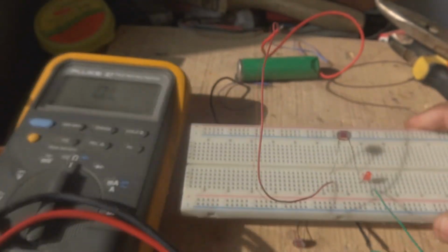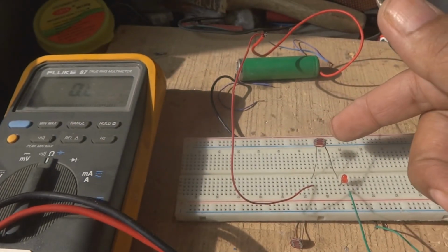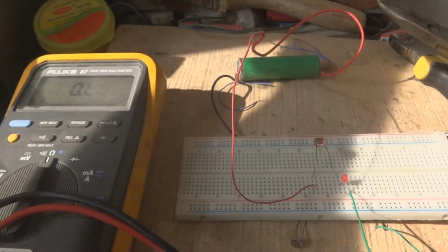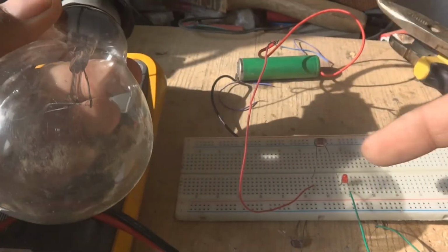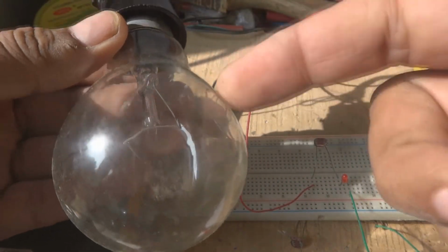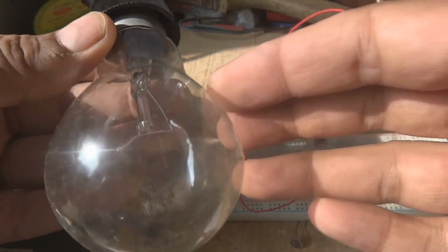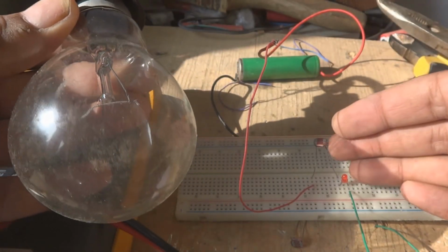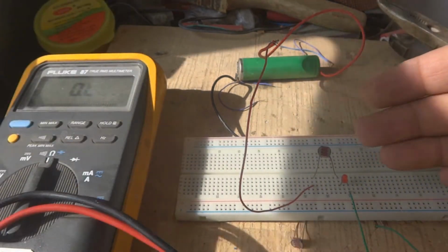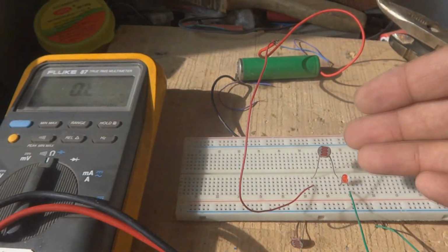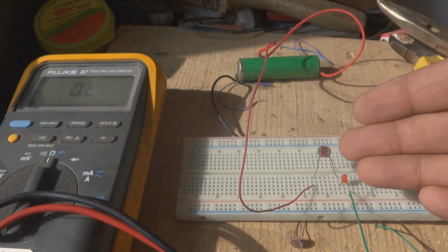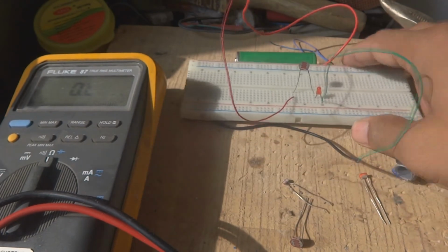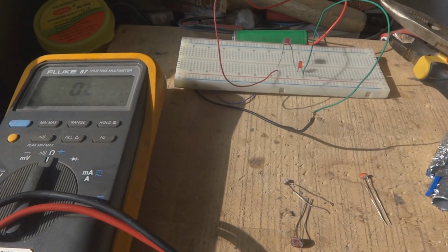This was a small experiment we made, but this is not efficient. This is not sufficient to control a 220 volt lamp or something. You cannot control a 100 watt 220 volt lamp using this by series connection. Instead, if you are going to switch this lamp on and off, you should have some other components like relays and triacs to connect it. Through those relays and triacs you can control a heavy load like 220 volt 100 watt, or more than 100 watt load.